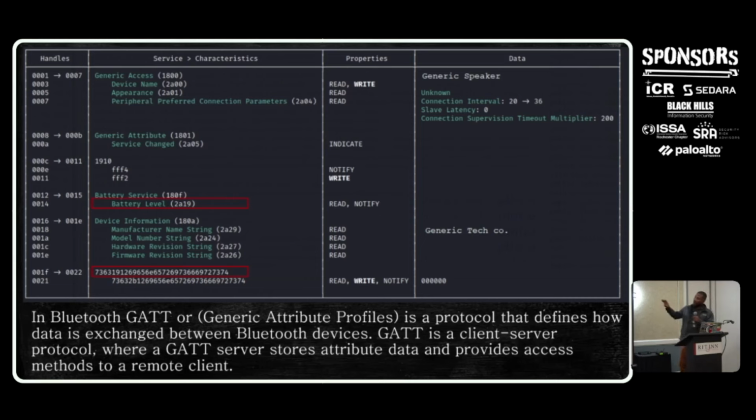And the Bluetooth specification, like a web server running standard port 443 or port 80, defines use cases. For example, you see battery level, and you see 4 characters. That's actually a shortened UUID, where you're only getting 16 bits of the whole long string.